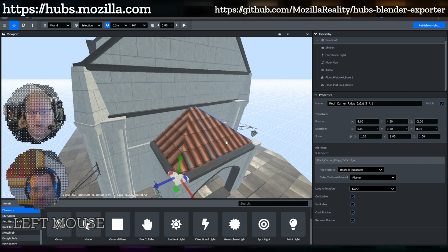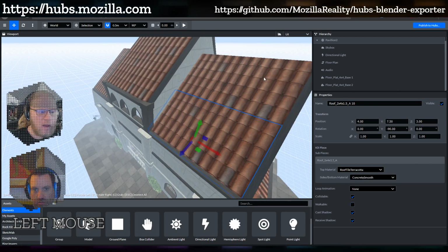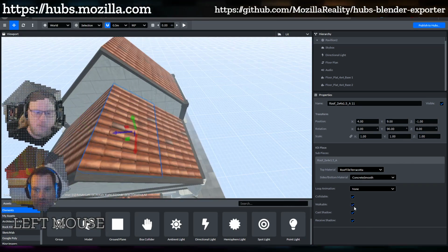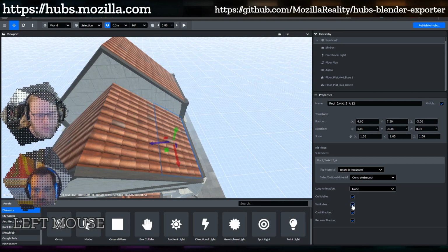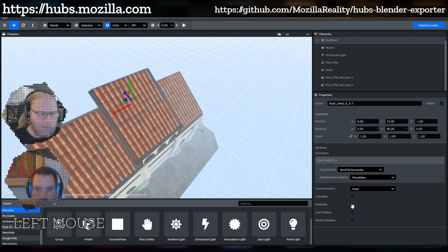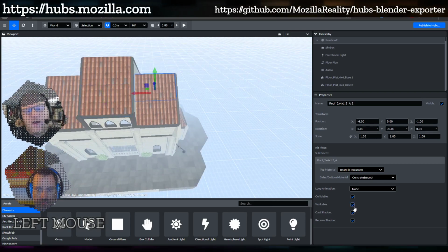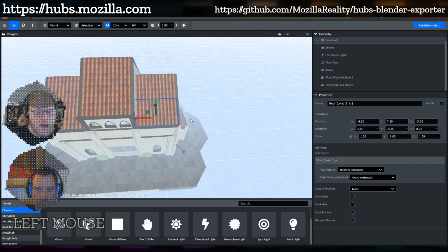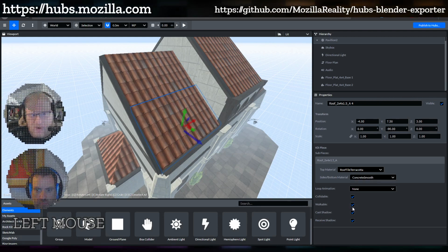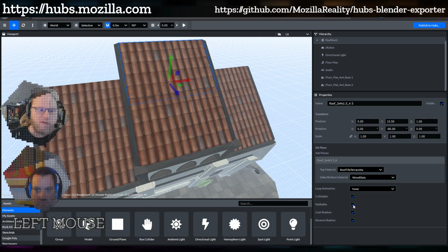It's actually a good idea to turn it off for anything, even if you're not really having problems. It'll speed up the export time, and also prevent you from running into issues. Sometimes I've seen people have problems where it'll go to export and it'll run out of memory or something like that, because it's too big. Really often large scenes, they'll have their skybox set to walkable, for example. And so then it's making this entire thing a nav mesh, and it has to waste a whole bunch of time and memory trying to figure out where you can walk on the sky, and obviously you just shouldn't be able to walk on the sky, so you should turn that off. And because we turn it on by default, people run into that, which is not great. But turning it off on anything that doesn't need it is useful.